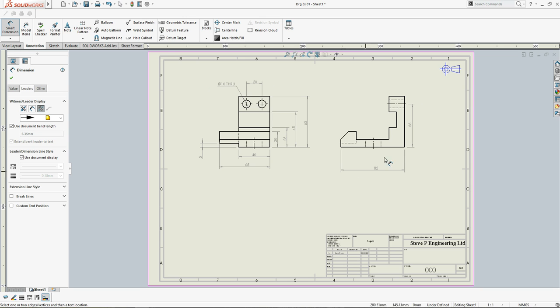What else do we need? Well, I need some dimensions on this side, so actually you can do with a dimension on there, 20 mil. Be nice to have this dimension shown here. Distance to the hole. Drag this one down a little bit, and a dimension from there to there, and basically I've got my dimensions in.